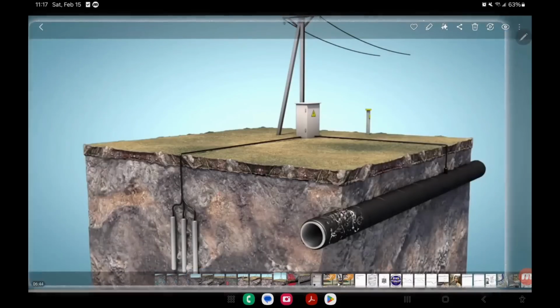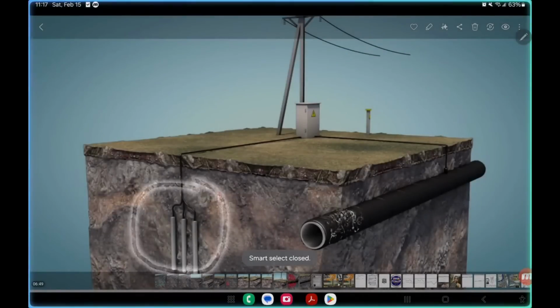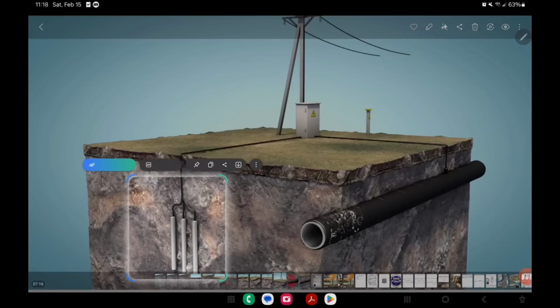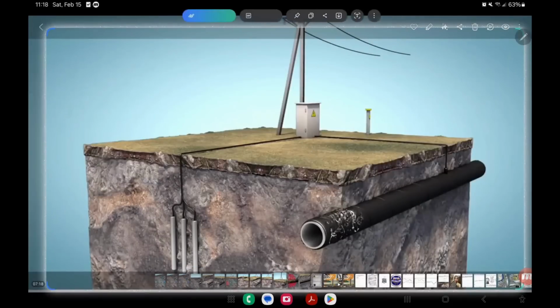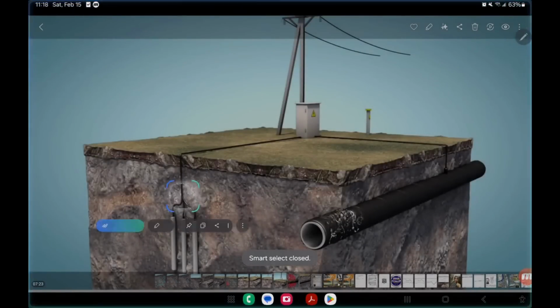If you see this, these are our anodes of cathodic protection. These anodes can be of iron, silicon, magnesium, chromium, zinc, aluminum, MMO. It can even be scrap, waste metals, up to old pipes. In this case, we see that they are anodes, vertical, and they are connected to a common point, which would be this common point. It would be this point here.